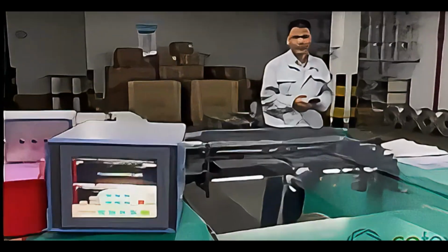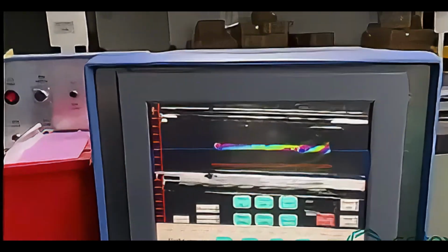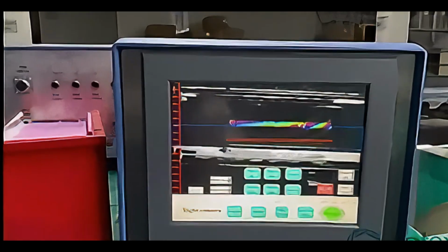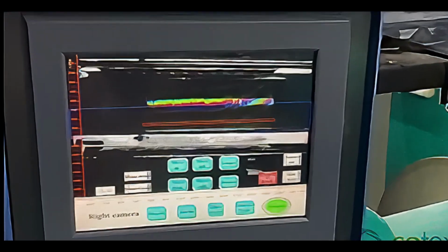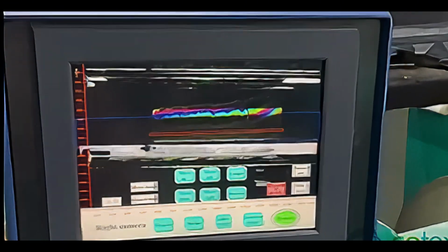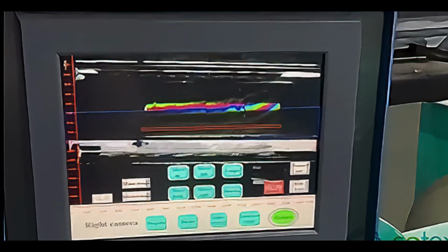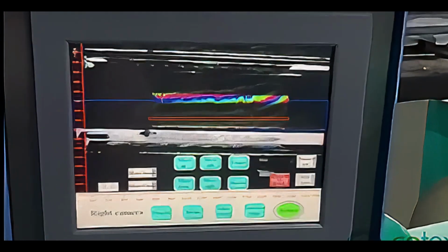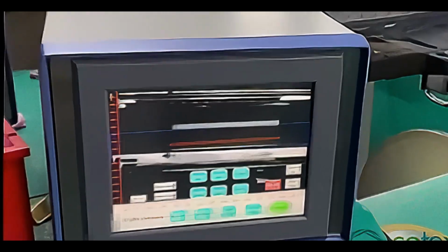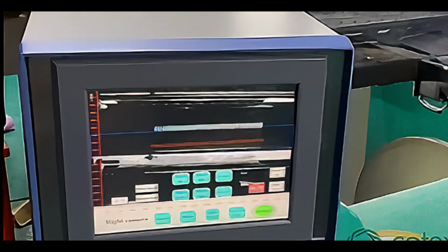We divide the color bar on the screen into 3 parts, the left, middle and right parts. Now, by slowly rotating the lens, the colors of the left, middle and right parts are evenly distributed, so as to achieve the highest definition of the camera lens. In order for everyone to have a more intuitive experience, we first rotate the color bar part back to a blurred state, so that the detected effect will be poor and very blurred.